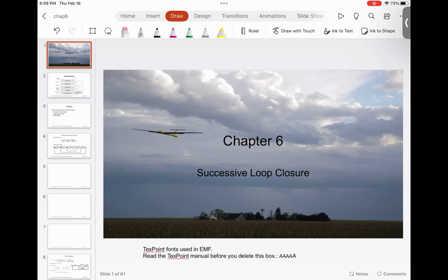And please understand, if you are into RC flying, you can fly the aircraft using the joystick control, but the aircraft would have internal stabilization flight control. And the only thing that internal loop is going to do is it will stabilize the aircraft. If it's a quadcopter, it will make sure it is in controlled hover. If it's a fixed wing, it will make sure that it is in the level flight. And then you can trim the aircraft and then actually maneuver the aircraft, or for that matter, quadcopter.